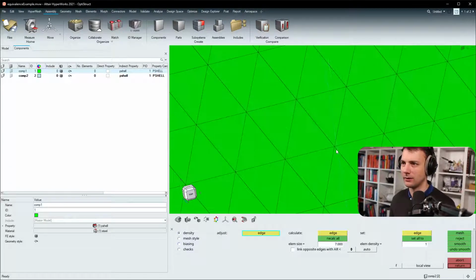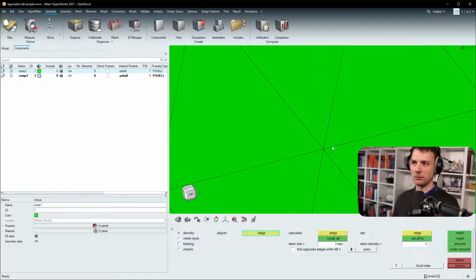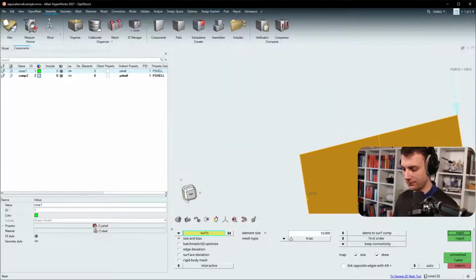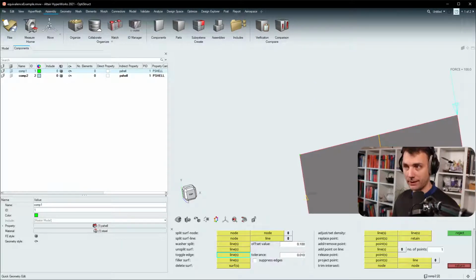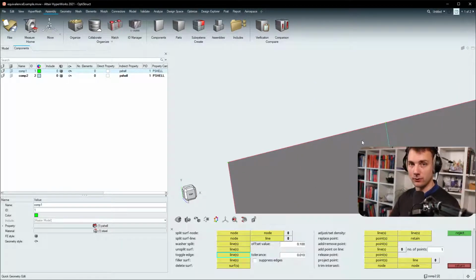Yeah, you see, it does not respect that line anymore, which it would with having that line green. So how to get back from a blue dotted line to a green to two red lines? You just press Shift and then click again. So I shift clicked on it, so it is green now.